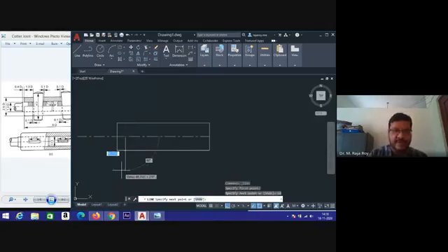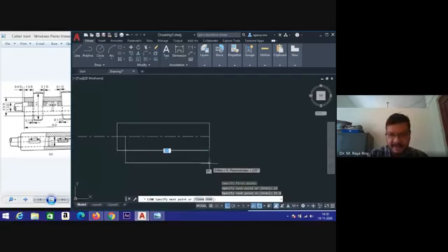Then move in the downward direction. The downward distance is 2.5 into 30 divided by 2. That is 37.5. 37.5 distance you can move. Okay, and you can track this point like this. So this is called tracking. You can track the point with tape.